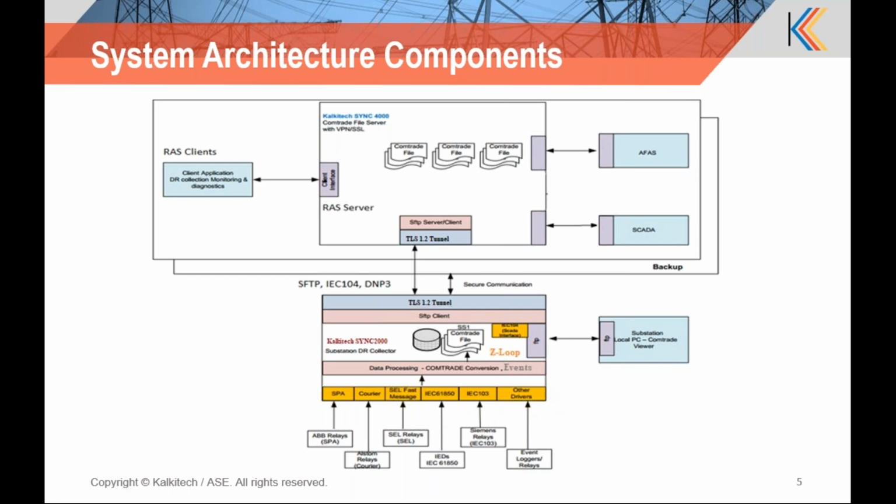The collected disturbance files are in their own proprietary format. We convert them into the COMTRADE common format and push this file to the central system over secure FTP.